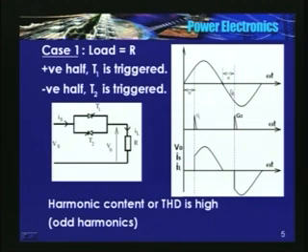So input voltage becomes 0 at omega t equal to pi. At that instant, even V0 becomes 0, Is also becomes 0, the load current also will become 0. I am assuming the device is ideal. So from omega t equal to pi up to pi plus alpha, there is no current flowing in the circuit. Load is purely resistive, that is the reason. And yet again at pi plus alpha, T2 is triggered, and negative voltage is applied to the load.